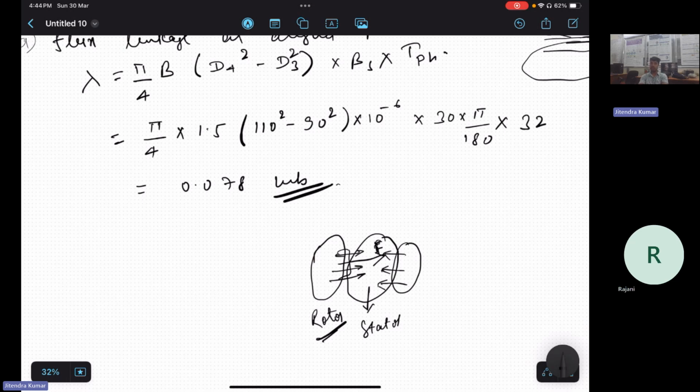Also, there are a lot of papers that compare the efficiency between this and radial flux, and it is not straight away advantageous. Otherwise, all vehicles would have axial flux machines by now, because there are a lot of designers and industry. We would expect many vehicles to have axial flux motors, but this motor has existed for more than a century, so that's one reason why it hasn't been adopted widely.